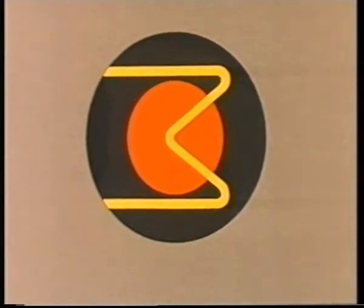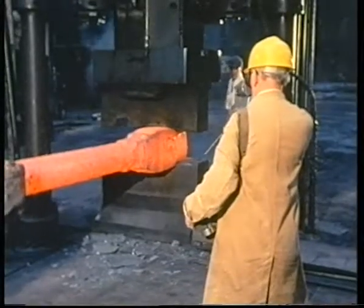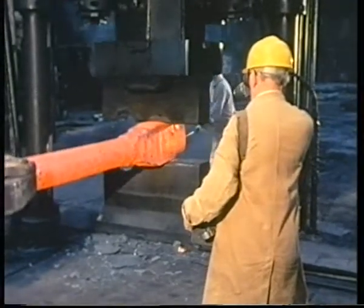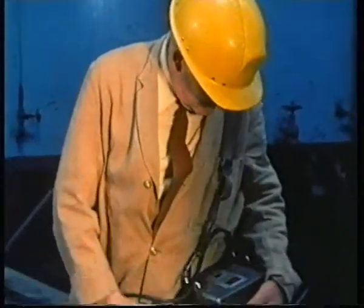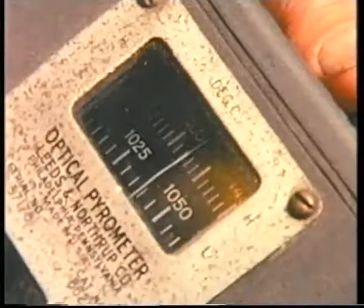As we increase the current through the filament, it changes color. The object is to make the wire the same color as the component. This will have the effect of making the wire disappear. Well, almost. All that remains is to read the temperature from this dial.